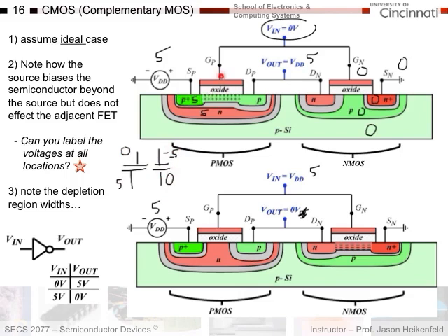And that helps me understand this, because if I have minus 5 volts here, a negative charge with respect to this side, I get positive charge on this side. Yep, that makes sense because I need to build up a p-type channel. So again, I have my 5 volts here, which I had figured out before because the p-n junction is forward biased. So here's my 5 volts, here's my 0 volts. 0 and 5, I said, is the same as minus 5 and 0.